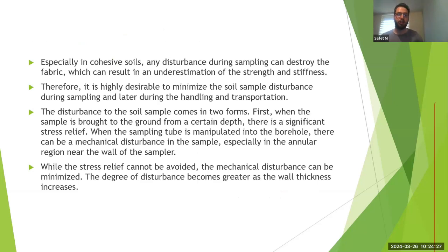Especially in a cohesive soil, any disturbance during the sampling can destroy the fabric, which can result in underestimating the strength and the stiffness of the soil. Therefore, it's highly desirable to minimize the soil sample disturbance during the sampling and later during the handling and transportation to the lab.